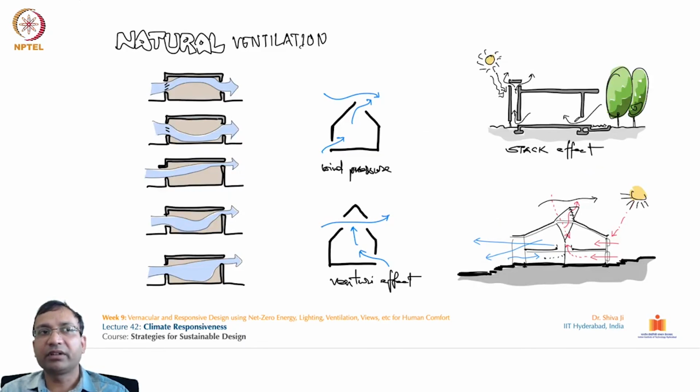Well, some more explanations from a different cross section, like how this hot air can be allowed to exit from the building. This has been done traditionally, and in recent times, with recent advances, it is being done in these buildings by using such fins at the top of the structure. This collects all of the stale air, and it releases it into the air from the topmost portion of the building.